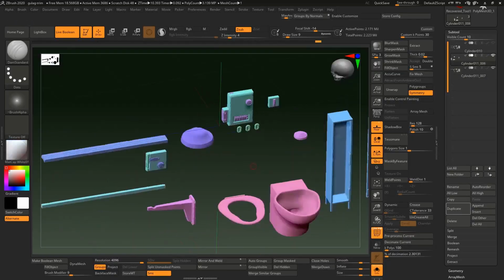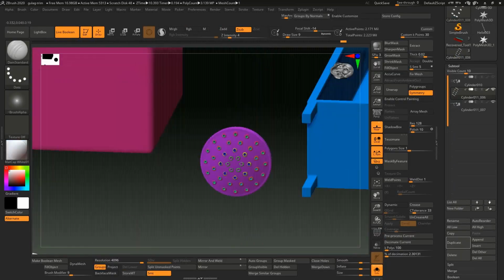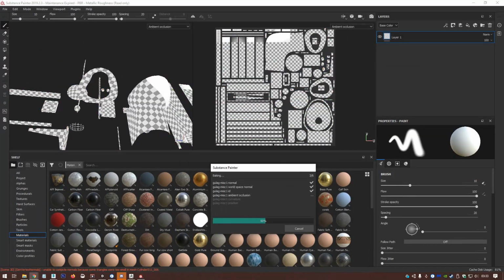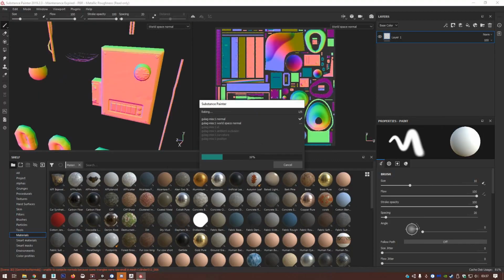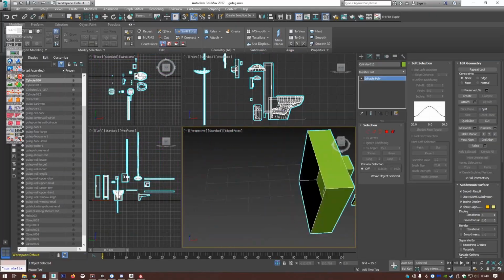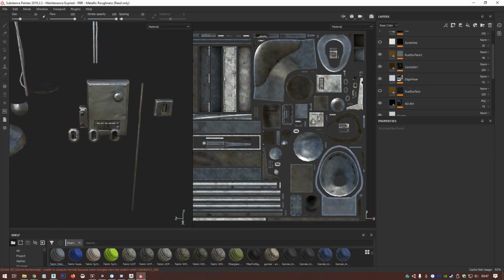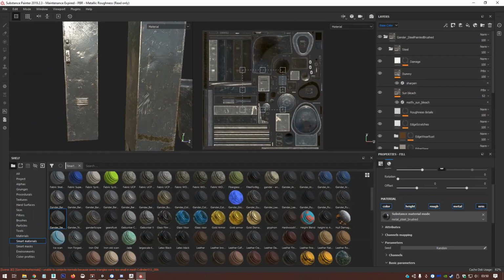Now I'm going in and grouping everything up, giving it ID for masks again. Doing a bake, fixing things, doing another bake. I actually figured out I had to add edge loops on the low poly model so that the average normals at corners did not skew the detail that was being baked.